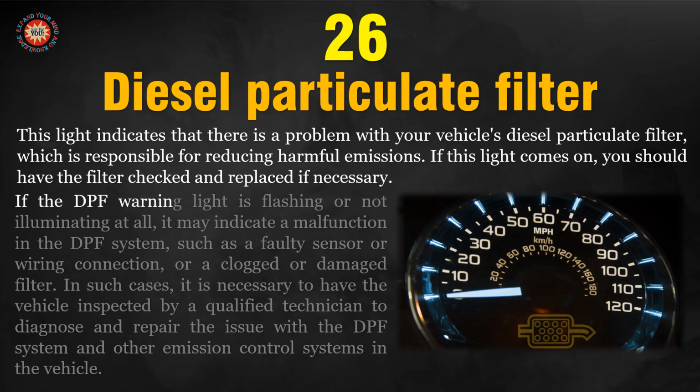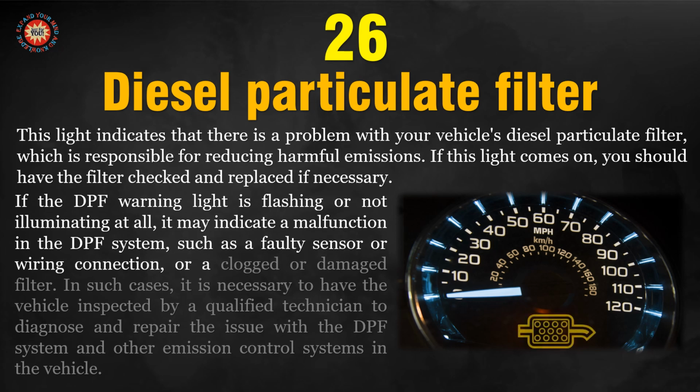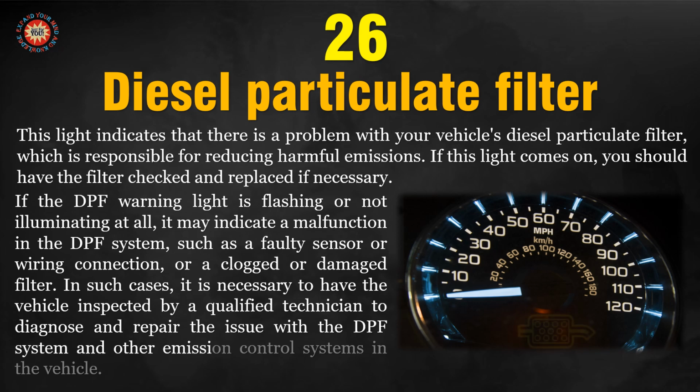If the DPF warning light is flashing or not illuminating at all, it may indicate a malfunction in the DPF system, such as a faulty sensor or wiring connection, or a clogged or damaged filter. In such cases, it is necessary to have the vehicle inspected by a qualified technician to diagnose and repair the issue with the DPF system and other emission control systems in the vehicle.